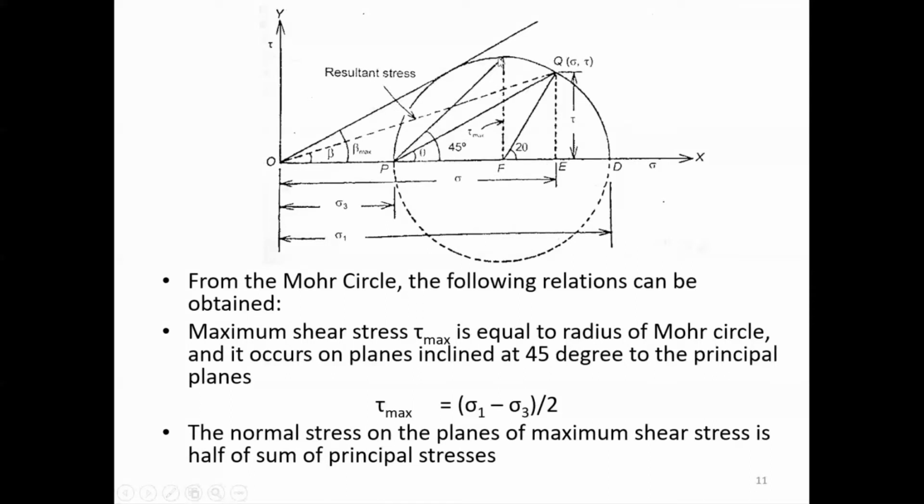So I found out where I will have my maximum shear stresses. It will be on a plane inclined at 45 degrees, and sigma will be sigma 1 plus sigma 3 by 2, that is OF.